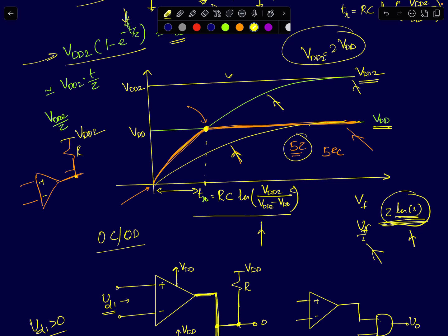So one interesting thing to notice here is that by using a diode, I was able to build an RC circuit which was able to reach its final value in a finite time. Even theoretically, it has reached its final value in a finite time. If you took a conventional first order circuit, the time it takes to reach its final value is infinity, ideally. But here I was able to reach its exact value in a finite time. Such things are possible if you use diodes.